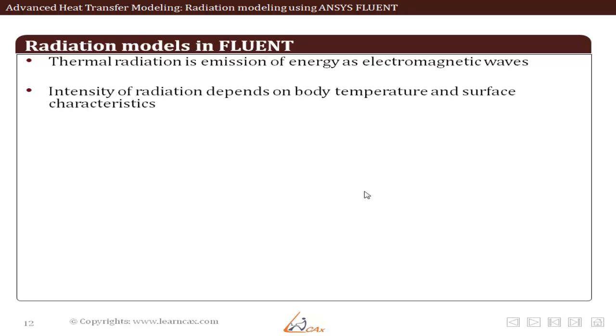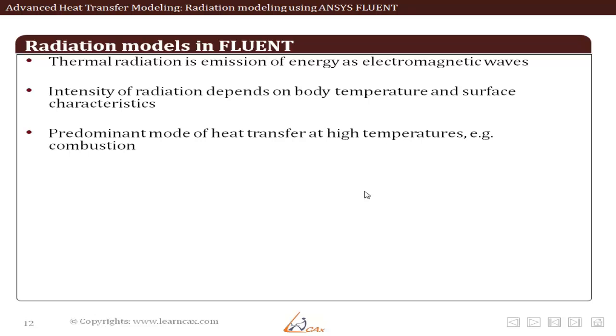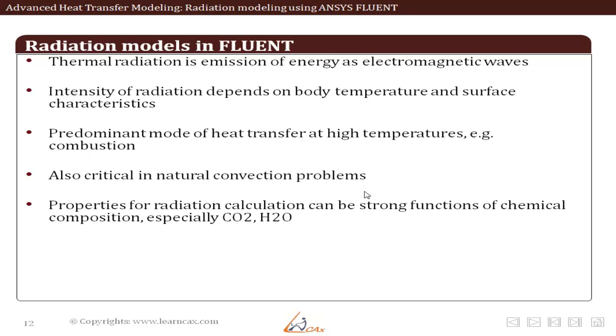First, let us see where we use radiation models. It is not necessary to use radiation in all simulations, mainly because if the temperature difference between the hottest and the coldest points in the CFD model is low, that is below 400 degrees centigrade, radiation heat transfer is negligible compared to other modes of heat transfer like conduction and convection.